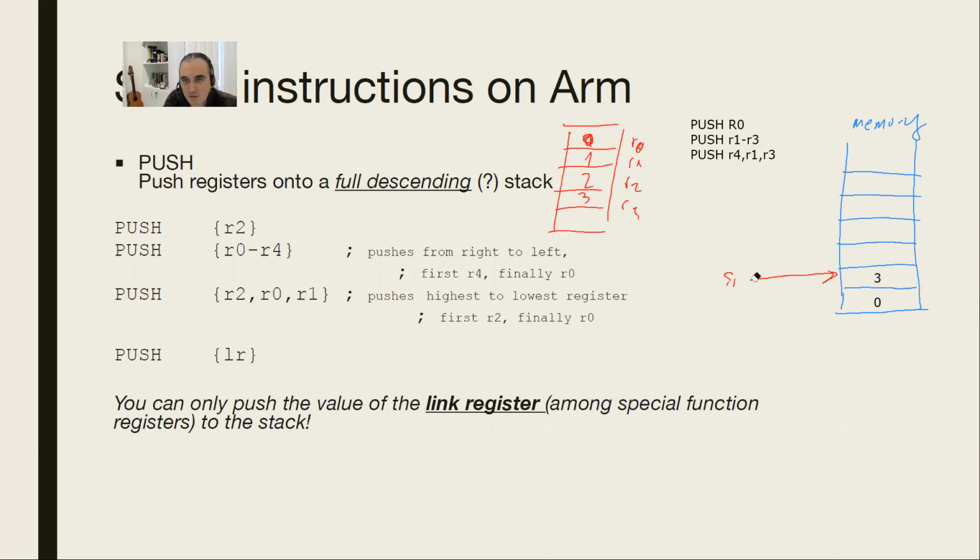Now, guys, the stack pointer is pointing to the next location. Then R2. Now the stack pointer is pointing to the next location. Then R1, and the stack pointer is pointing to the next location. I have done 3 push instructions together.